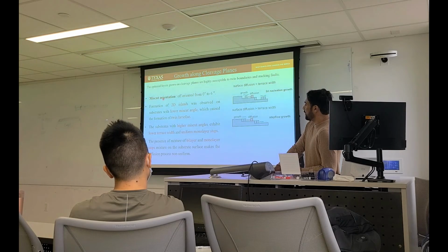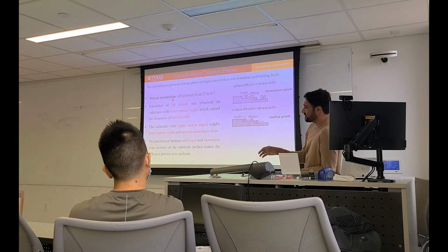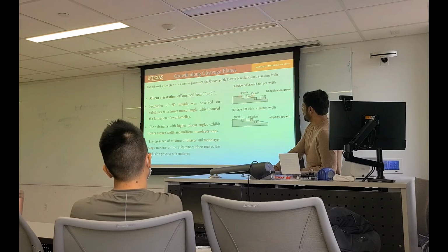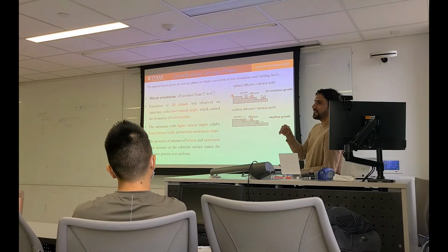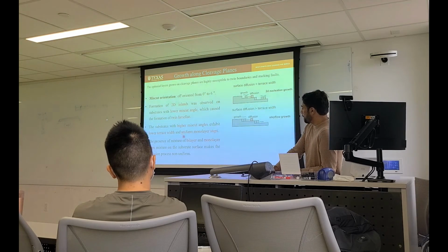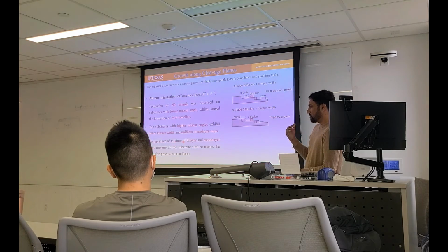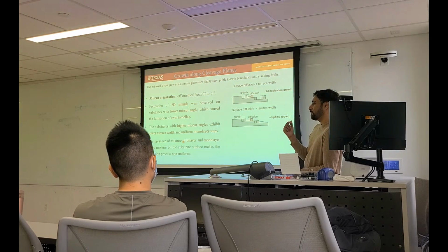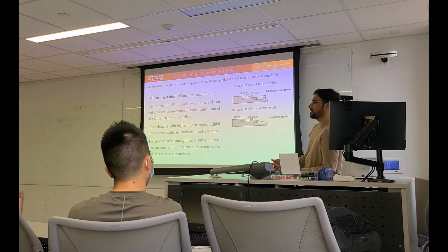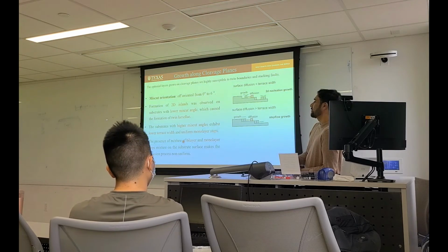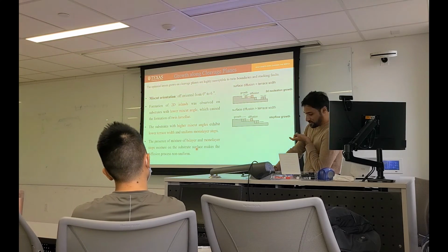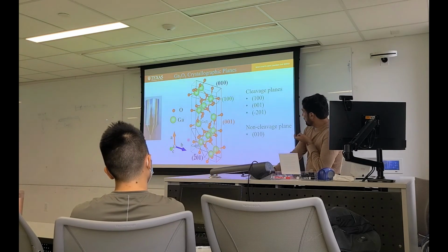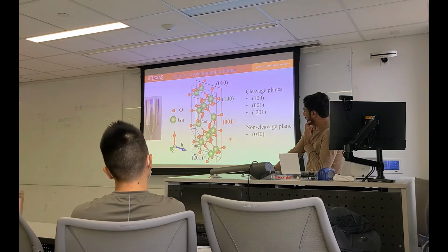So when they cut the substrate at a different angle, that means they are changing the terrace width. Then you are well aware of monolayers and bilayers. If your substrate has a mixture of monolayers and bilayers, that means your crystal will not grow with good morphology. You can grow, but the morphology is very bad. So they cut it at different angles along a specific direction. Suppose they cut it along the 2 by 1 direction.